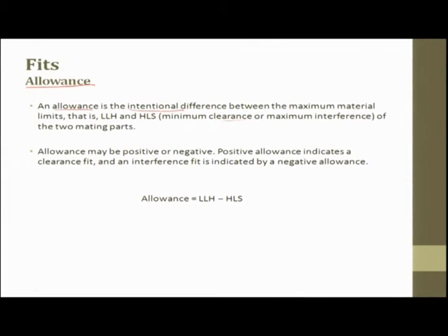Allowance may be positive or negative. Please make a note, allowance need not be positive alone, allowance can also be negative. Positive allowance indicates a clearance fit and negative allowance indicates an interference fit. This formula is very important, so in the examination there can be a problem asked in this topic.